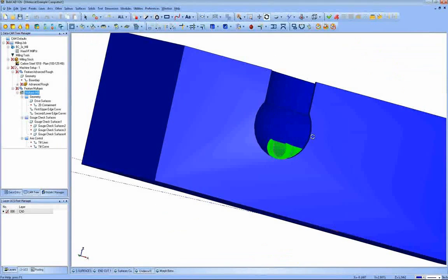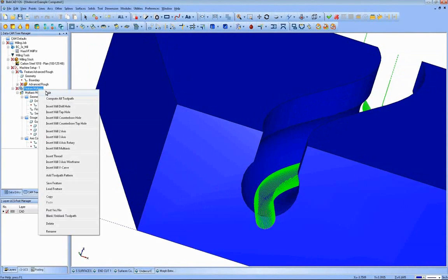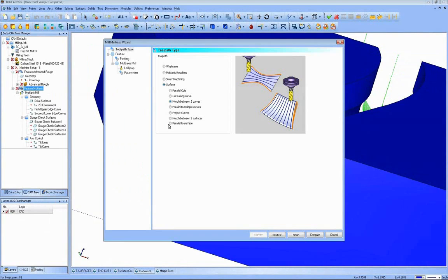One of the next things I want to cover is using the projection toolpath. If I just show you inside of this one before we actually bring up a model and create, we have a project curves toolpath. And if you look at the picture, you can see there's just a spline or a curve or a line that's flat, drawn above a curved or wavy surface.